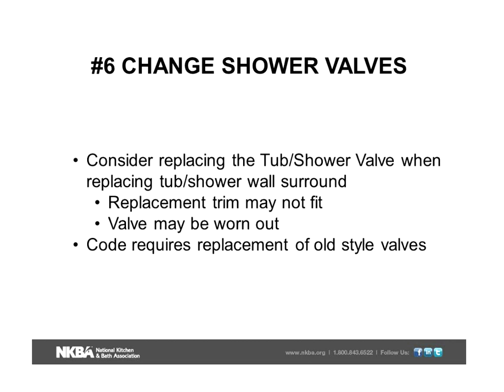Change shower valves. Now this brought up an interesting point, and it covered 2 different areas here. More than once I heard that when you start ripping the interior of that shower out to replace the surround, it's probably not a bad idea to go ahead and replace that older tub shower valve. Now we know by code, if it's tub shower or shower only, it has to be pressure balanced, temperature limiting, or a combination of both.